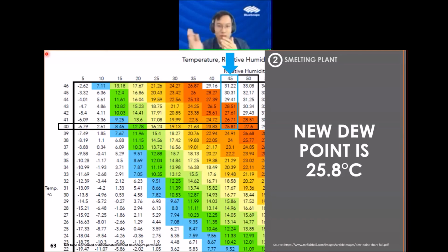Yes, because if you do it properly, removing all the corrosion product, meaning the rust and also the white rust oxidation, and then paint over it using a suitable paint in suitable conditions, cure it properly, and leave no gaps or leakages exposed to the same type of environment, then it could be a short-term solution.